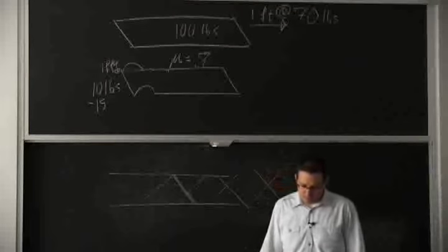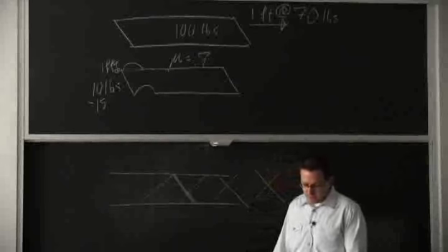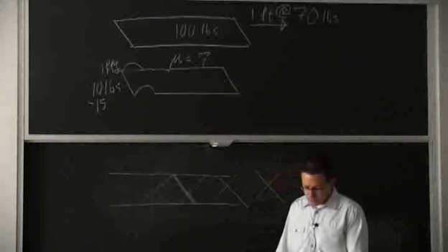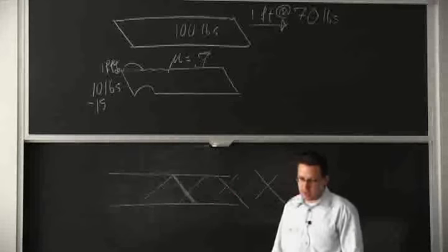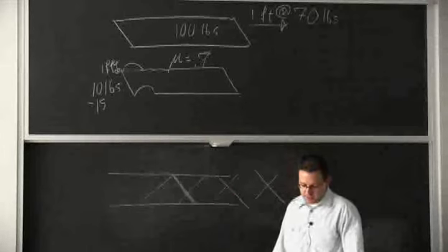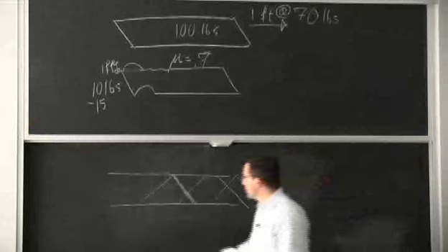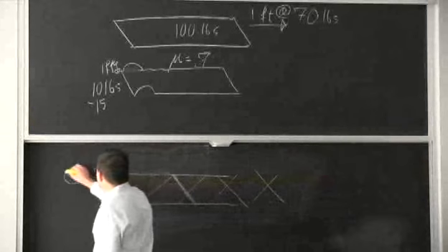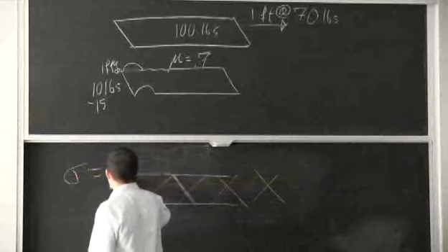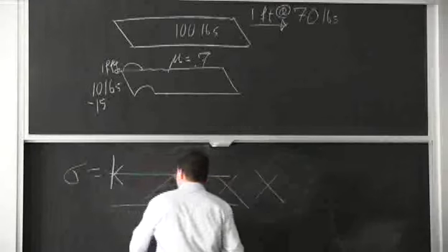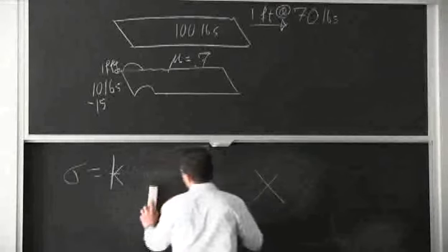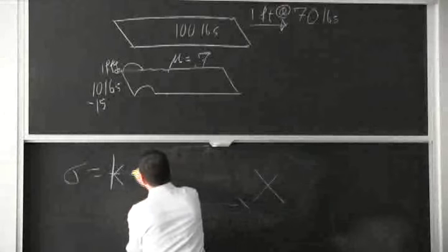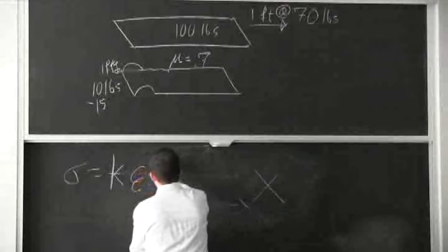And when you look at it from the stress-strain curve, when you average out all the deformation that's happening in the sample, we have this key equation of the stress. Typically it is a power law. So there's a constant that's defined from the initial yielding, and then you have an exponent to the strain.